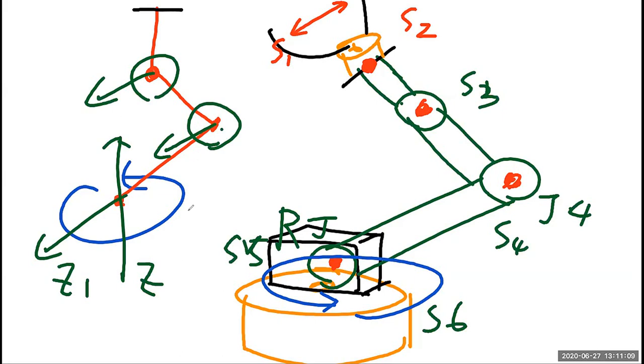And the X direction, you can define the X direction, and I don't think the X direction matters too much. As for A and D displacement, there is basically no displacement or prismatic joint. They are all revolute joints, and each one is described by an angle. And the close and release is not in the kinematic diagram model. Thank you.